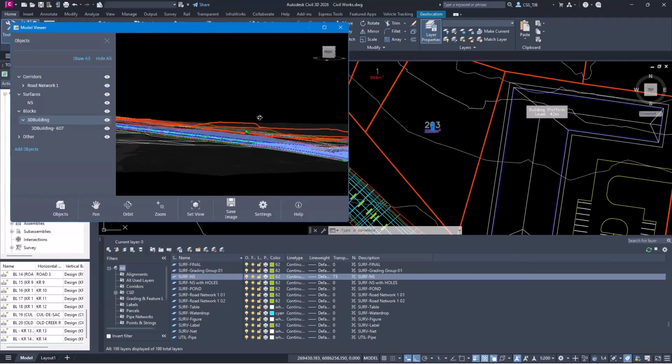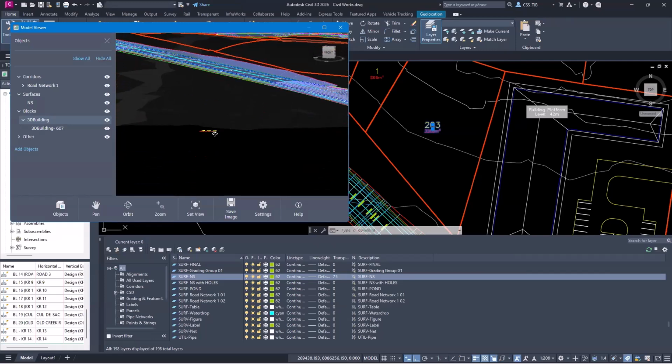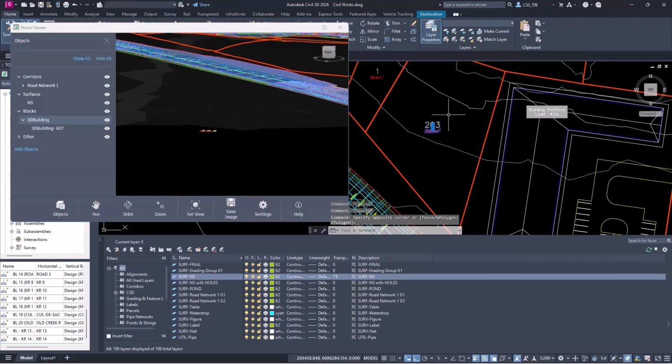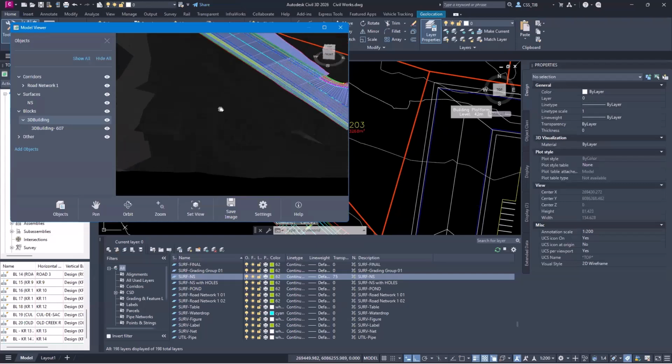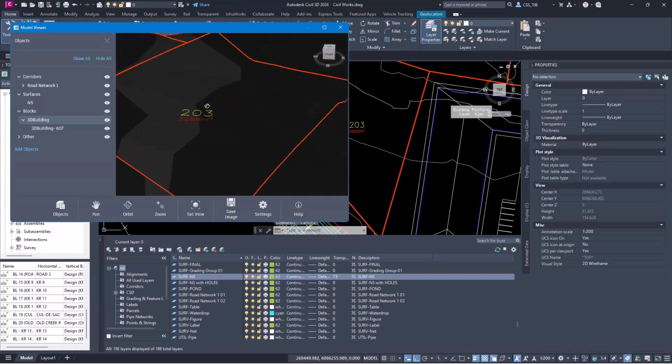If you look at it, it's sitting way down low at elevation 0. So that's what I was warning you about. If you do throw them in, you've got to make sure they have a height. I know this one should be about 42, and then it'll appear like it's sitting on the surface. So you do need to add them with some elevations, but they do show through.